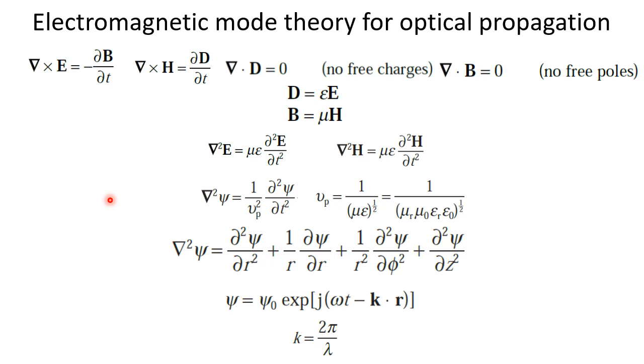Unfortunately, inside the core of the fiber, the core is of the order of few micrometer only, whereas the wavelength of the light is of the order of micrometer. Okay, under that condition, inside the optical fiber, particularly for small core optical fibers, transverse electromagnetic wave doesn't exist. So obviously geometrical optics will not hold.